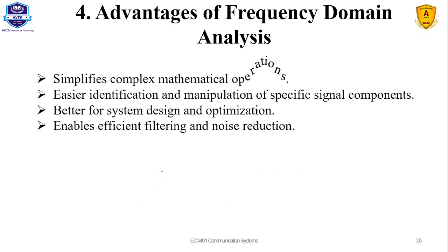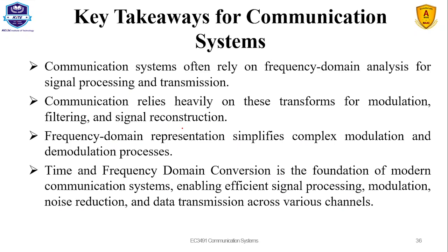So the advantage of frequency domain analysis is, as I said, it simplifies the mathematical operations, enables identification and manipulation of specific signal components, is better for system design and optimization, and enables noise reduction by filtering.